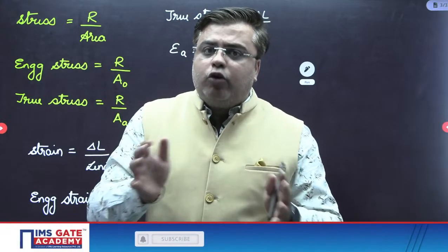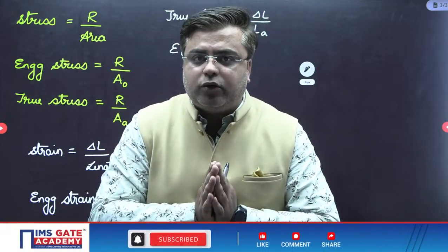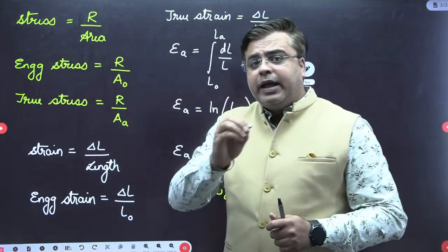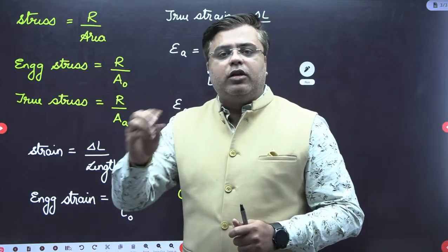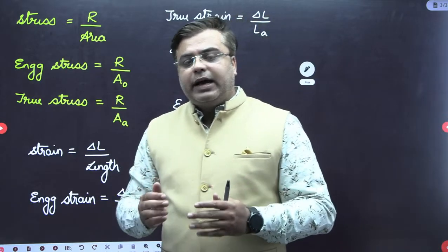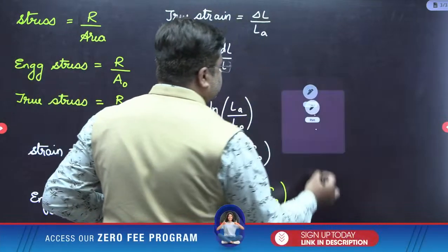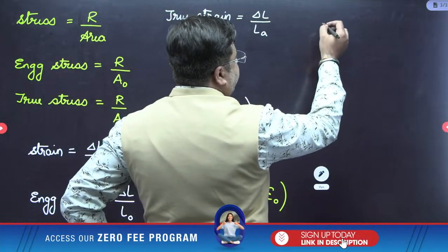When you combine homogeneous and isotropic material together, it means that the property of the material is the same at all the points in all the directions. Based on that, we have Hooke's law. Now sir, there are three Hooke's laws. First one is Hooke's law for axial loading.